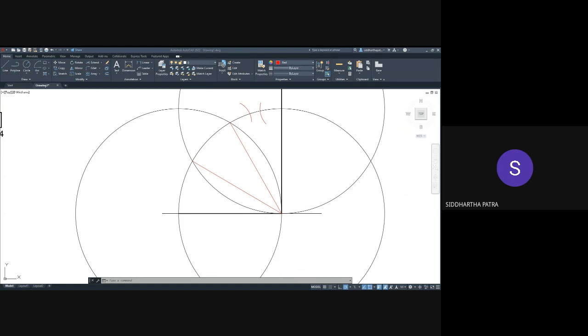Now once you figure out how much is the length of the chord, so basically the radius that you get from the compass, that is essentially the length of this chord, which measures 10-degree. So once you figure that out, you can use that for each segment. So you don't have to use trial and error for each segment. For one 30-degree segment, if you can figure out how much chord length corresponds to a 10-degree angle, then you can repeat the process.